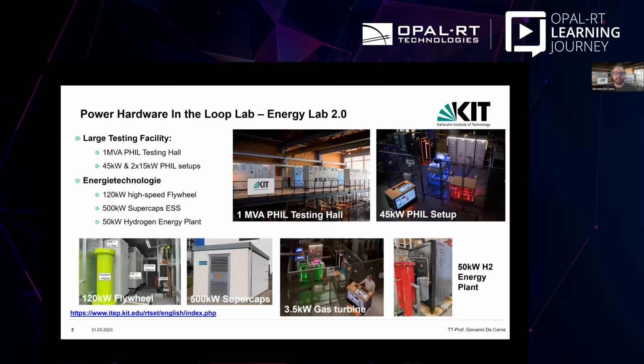What do we test? Well, we have different kinds of energy technologies. We have available a 120 kilowatt flywheel energy storage system with around 7.2 kilowatt-hours of stored energy, about 5 minutes of energy at full power. We are currently testing a 500 kilowatt supercap system of 1.6 kilowatt-hours. And we can combine these two together so that we can create hybrid energy storage systems.